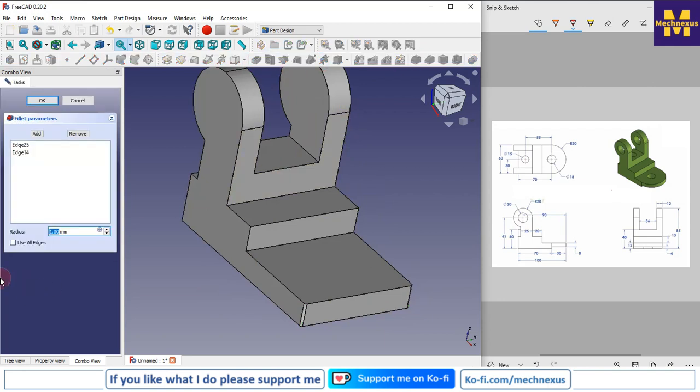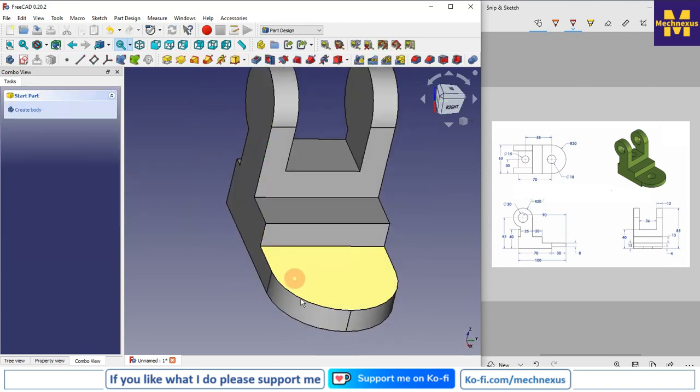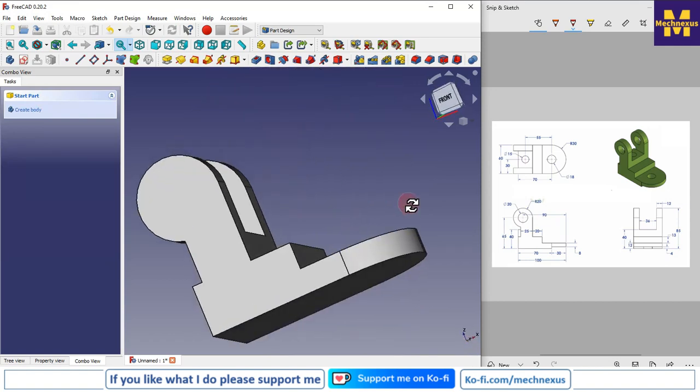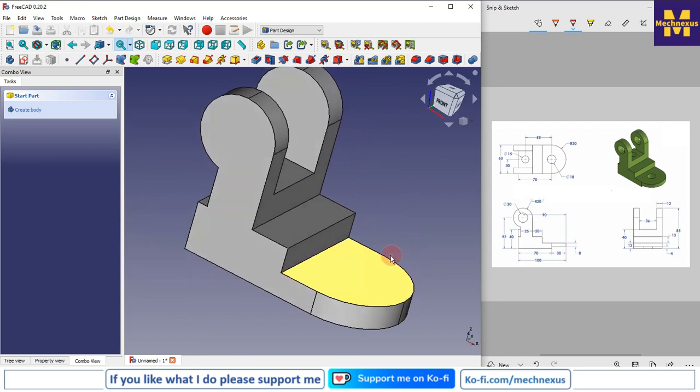and give 30. So 30 would not take because there is some problem with FreeCAD, and I face this problem many times. So what I will do, I will give 29.99. Now it will take without any difficulty, and I will say okay. Now we have made the solid features. Now we will remove the material.